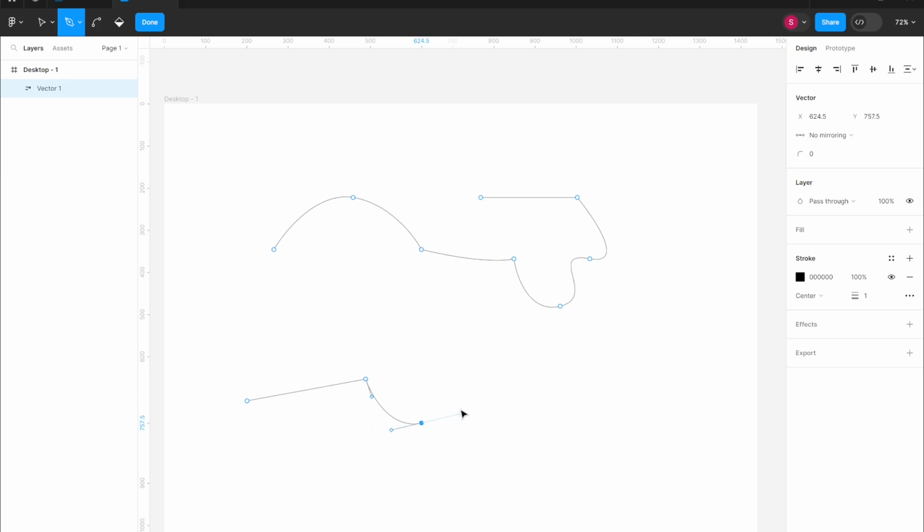Each active point, in fact, has two adjusters called handles, which respectively determine the shape of the previous segment, the left handle, and of the next segment, the right handle, representing the tangents of the segment. The handles determine the type of curvature of the segment. For each handle, we have two adjustments, the slope and the length.